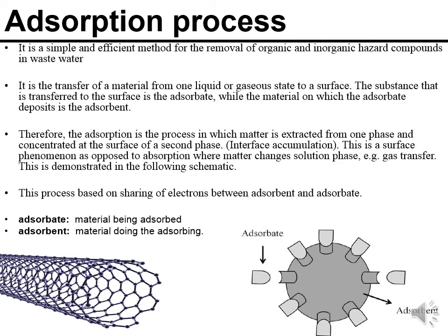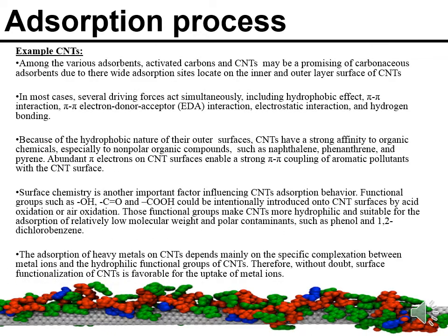In the adsorption process, there are a lot of adsorbents that could be used, such as silica gel, zeolite, and carbonaceous compounds. But the main criteria of the adsorbent must be stability and surface area, so carbon nanostructures, especially carbon nanotubes, are a prominent adsorbent material. But there are some considerations for the carbon nanotube surface, such as functionalization of carbon nanotubes, where the main problem is how to make the surface of the carbon nanotube active.